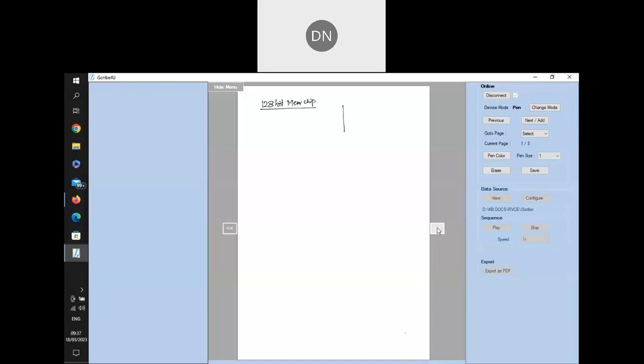When you purchase any memory chip in the market, you should identify immediately. I have taken a very small size only from a theoretical point of view. You don't get 128 bits, you get 2 megabits, 64 kilobits like that. Just for understanding, I've taken a small size. Any memory chip you purchase in the market, the first thing you have to ask is the size of the chip. Generally they tell the chip size in terms of bits, 64 kilobits, 64 megabits, like that. The chip I have taken is a 128-bit chip. So the first question I have answered is the size of this chip.